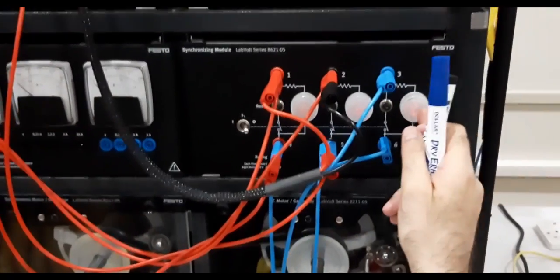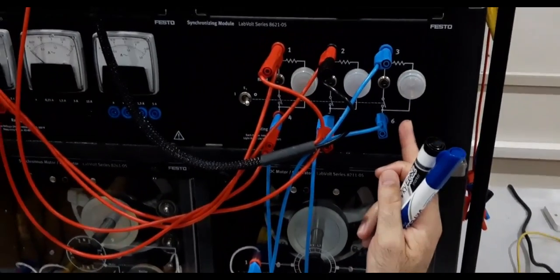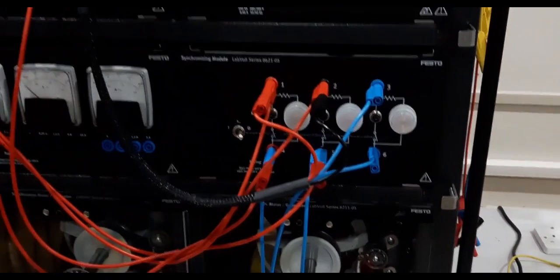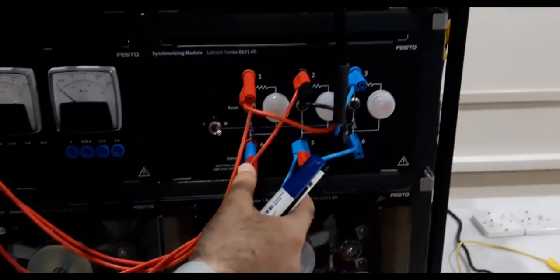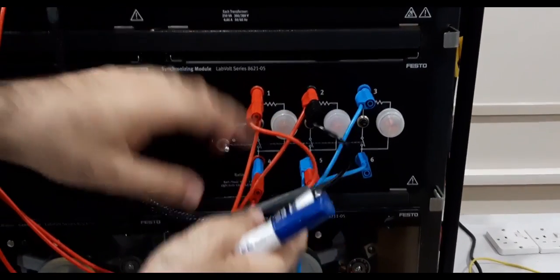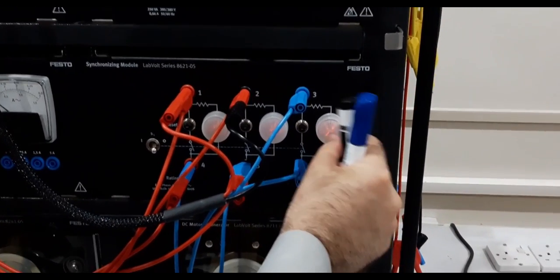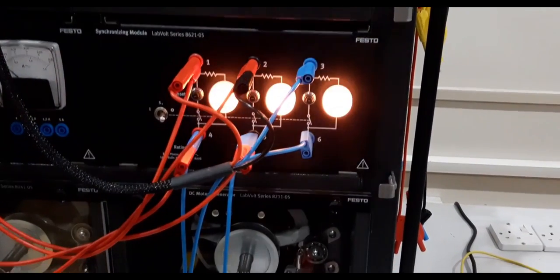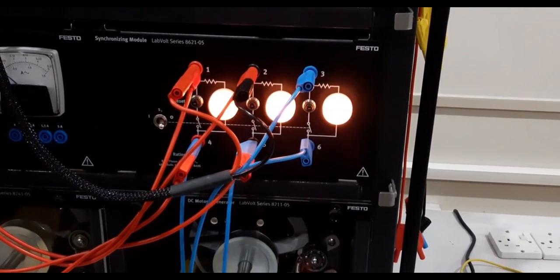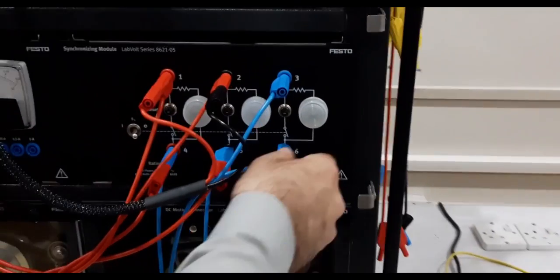So now you can see here, the blinking of the lamps is almost, there is no blinking. You see here? So once we have no blinking, it means that the voltage from the generator is equal to that of the system voltage, because if there was any difference of the voltage, we would have the blinking of the lamps. Okay, even one can check the phase sequence. Yeah, one can change the phase sequence.